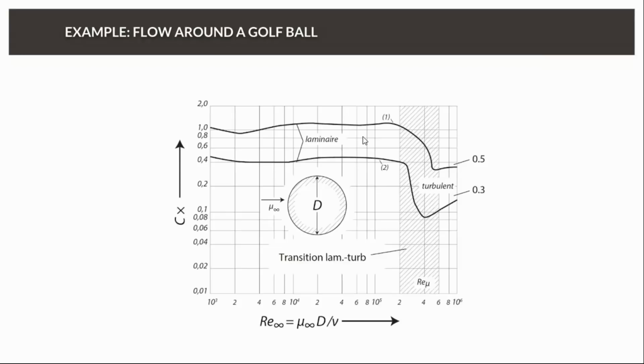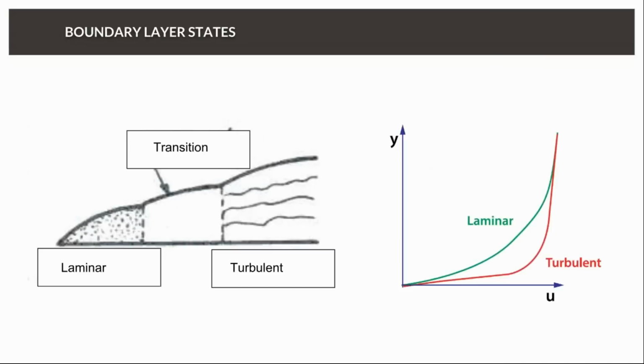And this illustrates that racing cars are working exactly like this. You have cockpits, you have open wheels in Formula 1, for instance. So these are regions where the flow will have difficulties to reclose behind. So there's risk of separation, and so risk of suction behind and creating a lot of drag.